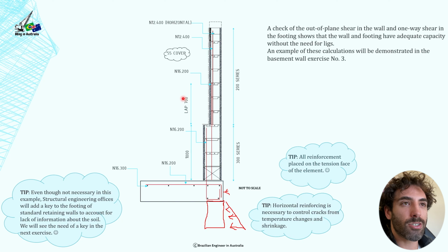So in exercise number 3, you also should check for this example. If you're doing a real life exercise, you need to check for the out of plane shear of this wall and also the one-way shear of this footing.